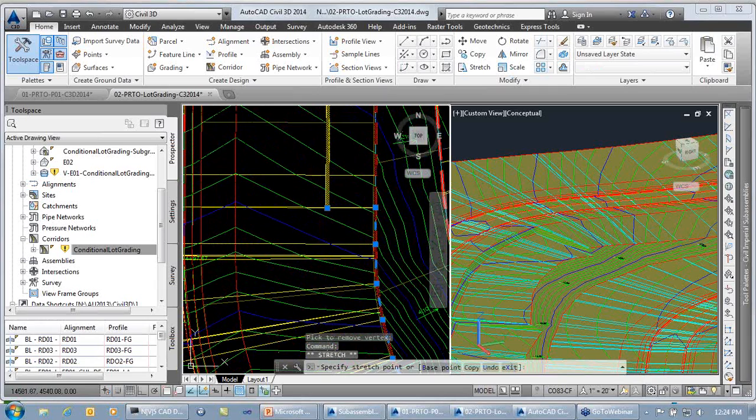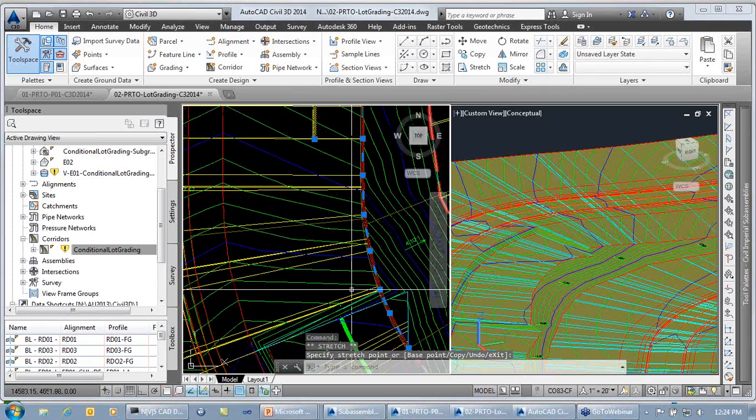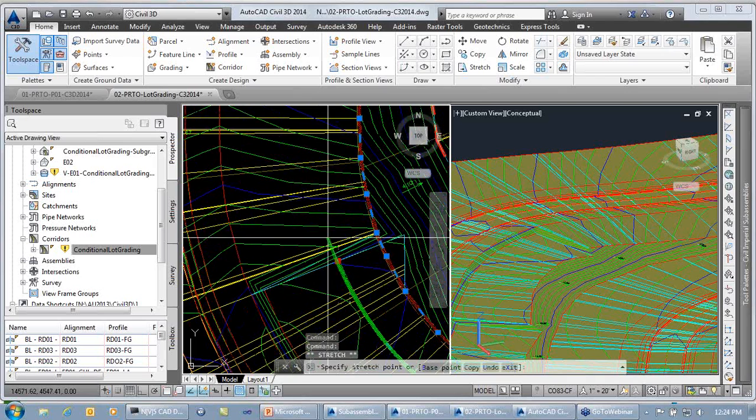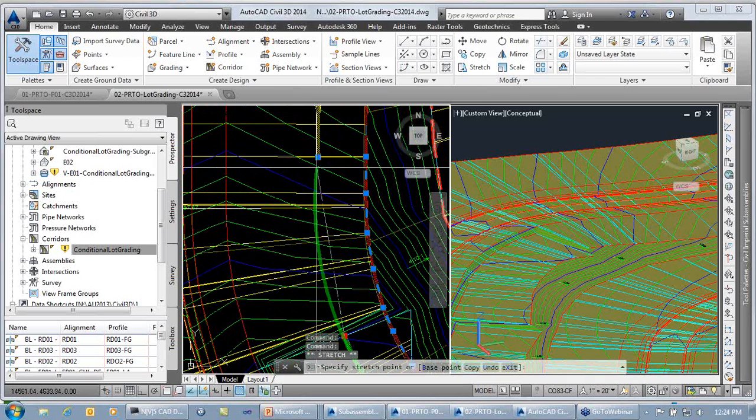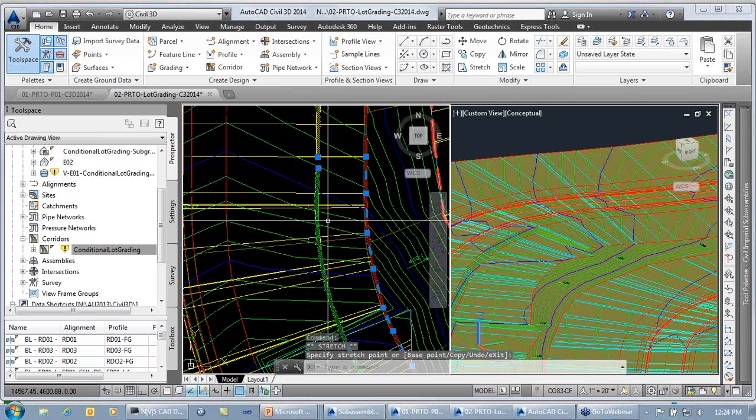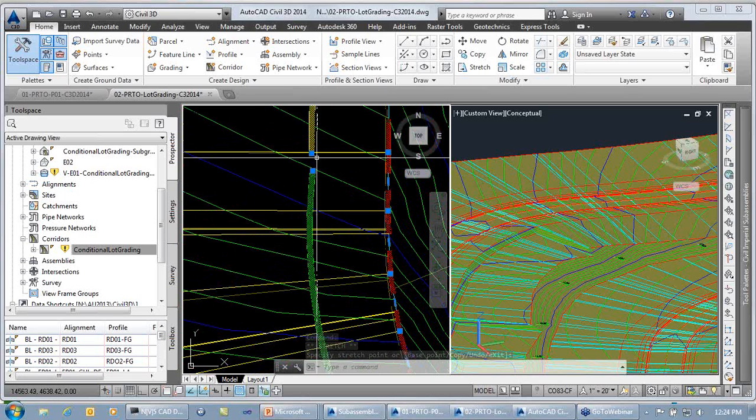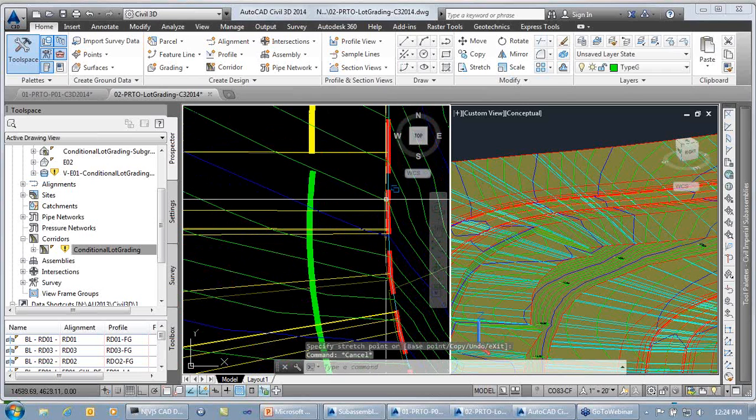I think I got a lot somewhere in there. I'm going to eyeball the 8-foot gap here. And what I'll do is I'll just take this one and then pull it around. There's my 8-foot gap. And I'm not going to worry about that it's not parallel. I just need to get the approximate shape. And if I want a true 2-to-1 slope here, I would just need to make sure that the distance between those two endpoints is 8 foot.